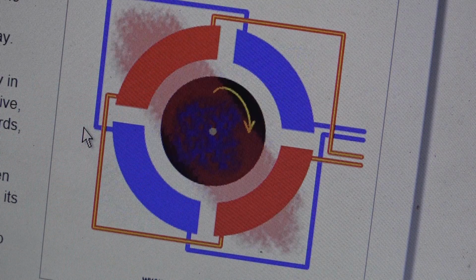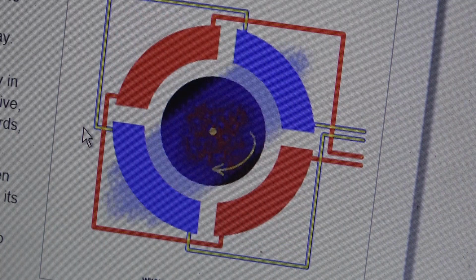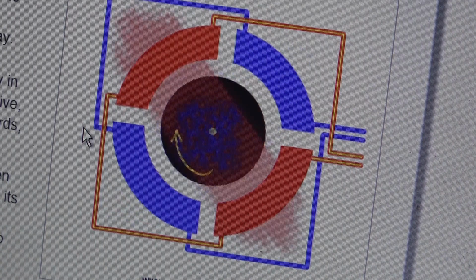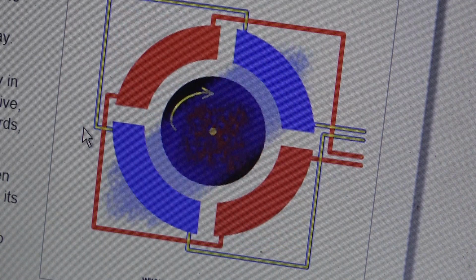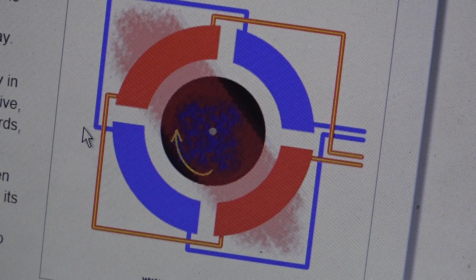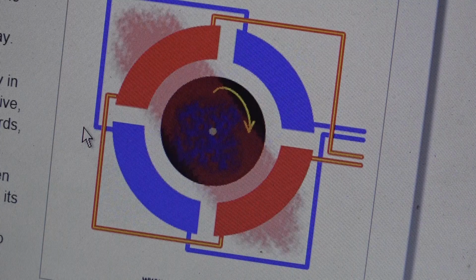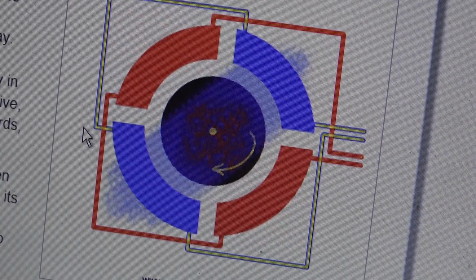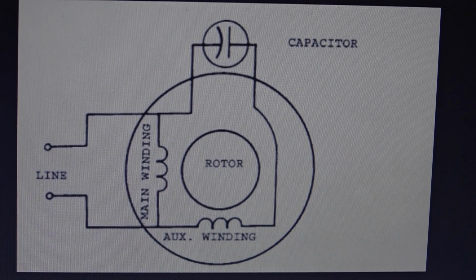How we do that is with the use of a capacitor. The size of the capacitor is selected based on the power and the rating of the motor. So sizing is important. If you go too big or too small, you could end up with a burned out coil. In this diagram we'll see the schematic, basically how a run capacitor is used on a low